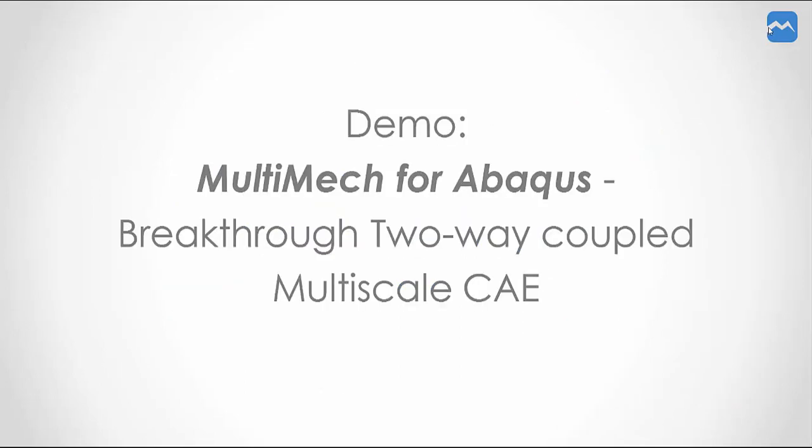For the past few years, this link has been done by combining Multi MEC's standalone, global, and local solvers. But due to numerous requests, we've finally decided to embed our breakthrough microstructure solution into an existing FEA solver, Abaqus. So a note on this integration is that we've not developed an analytical UMAT for composites. Instead, we've actually embedded a fully parallelized 3D finite element solver into Abaqus CAE. And to our knowledge, this is the first time this has ever been done.